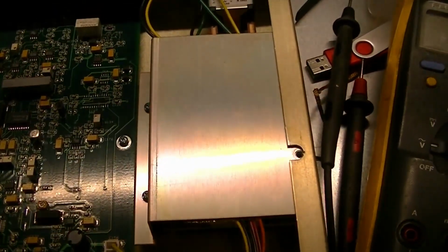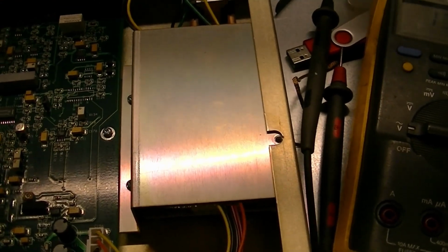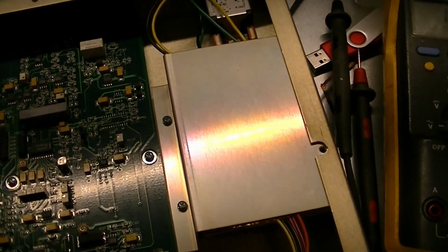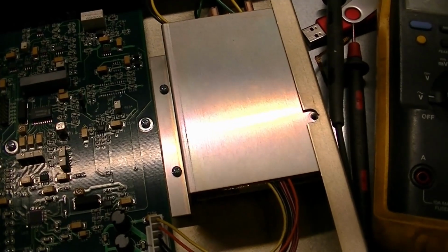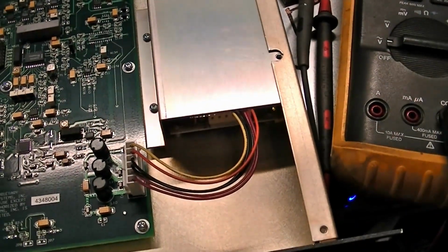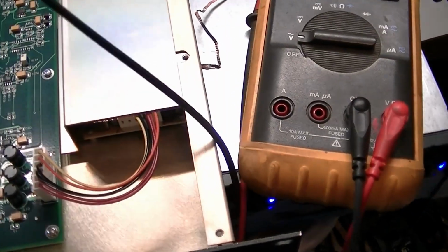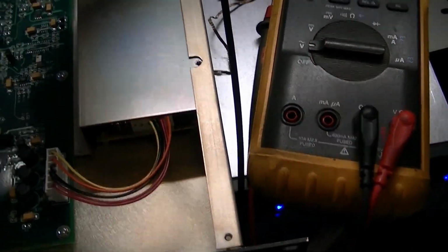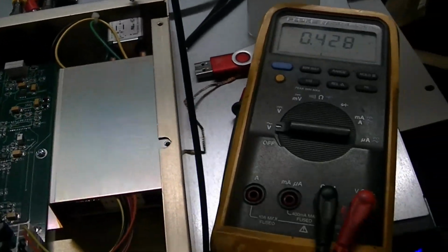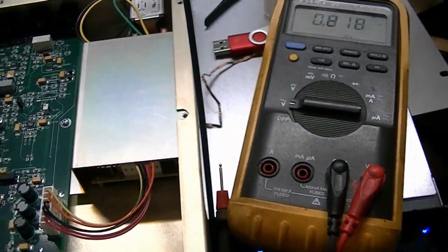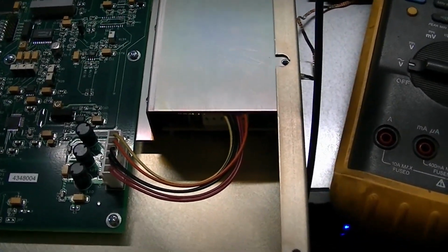So I'm probably going to say that seems to be a power supply problem, but let's take a look at it. Okay, so we have under this metal plate probably a 20-25 watt rated power supply module. This is where it connects to the main board here. So usually what I do here is I just put a probe in the chassis like that, assuming it's chassis ground. Your luck may vary.